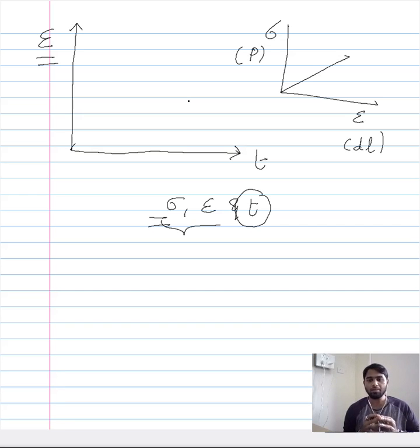Now when we talk about stress, we mean the mechanical condition we impose on a material. It doesn't mean that we are calculating the stress or using the actual definition of stress. When I say stress, it means the mechanical condition that we impose on a material, and that is the reason why we considered this plot here. When I talked about this plot, I meant the stress-strain curve or load-elongation curve. So in all these different variants, one is the condition that we impose, the other is the response of a material.